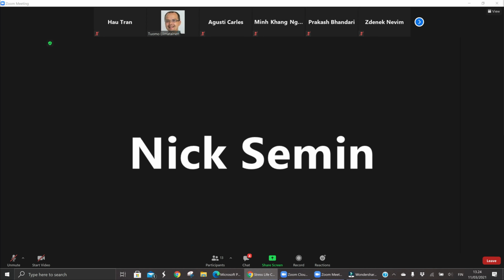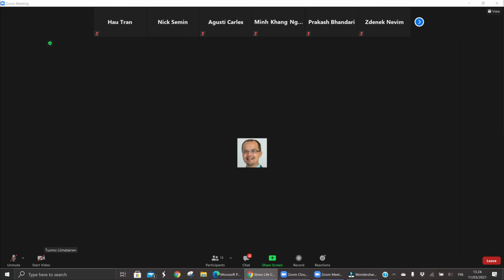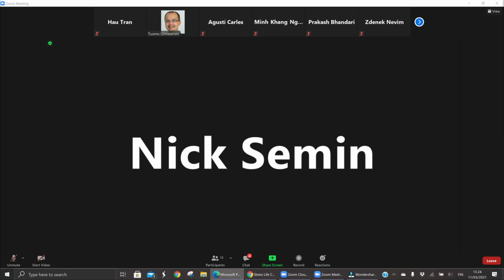Yeah, continue. Also you need to take into account that the x-axis for the surface finish effect is in KSI. So you need to use the conversion factor I gave in the task assignment, or alternatively, you can use a converter you can find on Google. If you, for example, Google KSI to MPa, you can find a converter for that. So we can just look for a table, right? We are not given any extra information in the task itself.